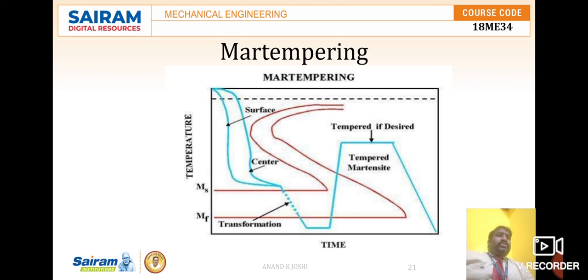In Austempering the steel is quenched to a temperature around 300 to 450 degrees centigrade, whereas in Martempering it is 200 to 300 degrees centigrade. And the transformation of austenite is complete in Austempering, and in Martempering it is incomplete. Also the process is limited to thin sections in order to achieve the fast cooling rate to transform austenite directly into bainite, but there is no such restriction in Martempering. And it consumes more time for Austempering, and here it consumes comparatively less. So these are some major differences between Austempering and Martempering. So let us discuss some other topics in the next video.